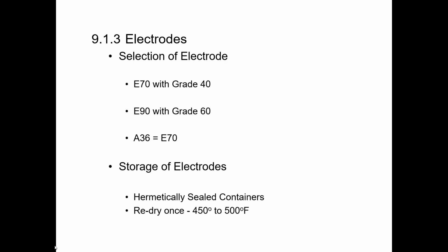Just to remind you, the only difference between the two is 706 typically has a lower carbon equivalent on average than 615, which is why we commonly consider it weldable. Because if you look, the implication of a lower carbon equivalent is a much, much lower preheat requirement, or in most cases even no preheat requirement for the bar sizes we're looking at. It's when you get into those higher carbon equivalent numbers that you see with 615 steel that you start to get into the more stringent preheat requirements. So yes, the table is for both types.